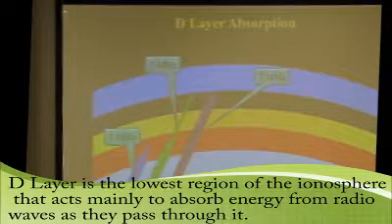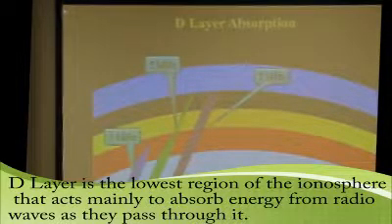We talk about the D layer. The ionosphere gives and the ionosphere takes away. The D layer can absorb different frequencies. In this particular case, it will almost always absorb in the 3 megahertz range, that would be 80 meters, and 5 megahertz up into 7 megahertz, which would be 40 meters. In that area, some of it can get through, but it winds up being attenuated somewhat. Then at, say, 40 meters, 7 megahertz, it may be able to go through without being attenuated at all.